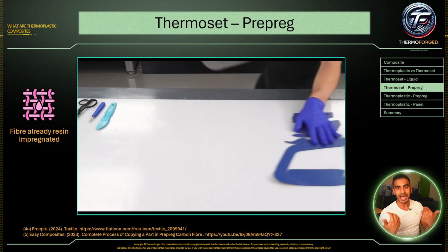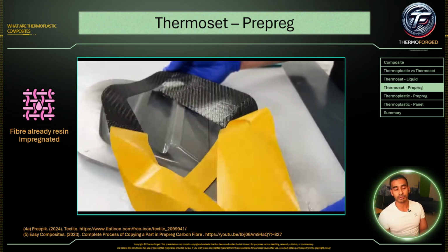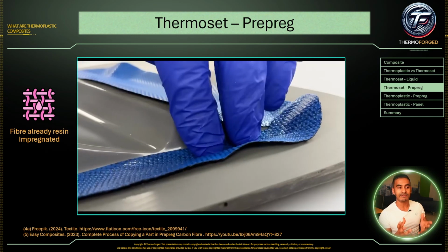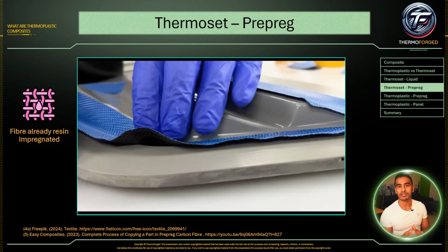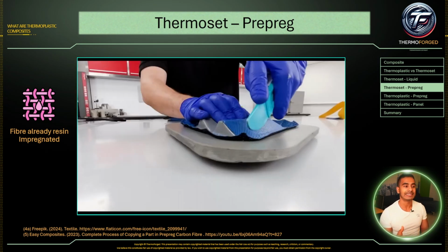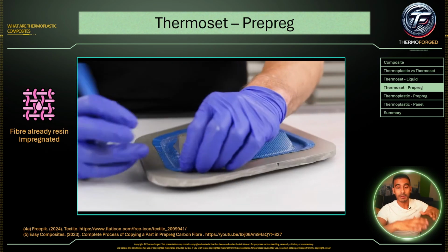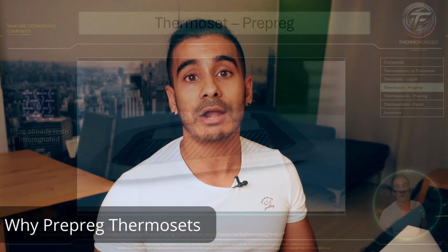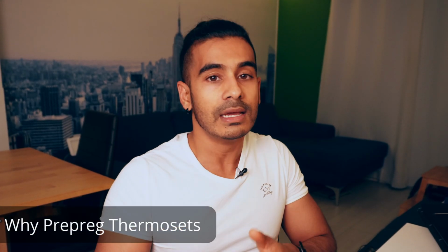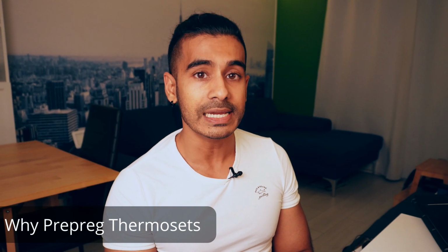And the material is encased between two layers of protective film. So you remove a protective film, and then you can see this shiny carbon fiber underneath, which is impregnated with resin, and the resin itself is tacky. So it's actually quite friendly for you to be able to place in a mold and push it down and position it. The barrier to entry into the skill set can be fairly low, so you can learn how to use this material quite quickly.